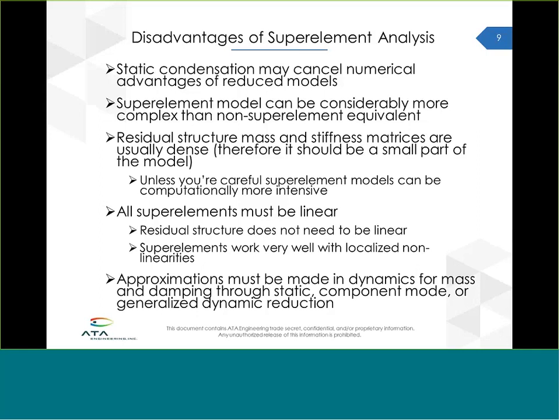Superelements must be linear, so you are reducing a portion of your model once and then combining them together, so the response of that superelement is always linear. The residual does not need to be linear, and I'll get to what the residual is, but that's what's left over after you've done all your reductions and combined them together. So the way that you combine two superelements together, you could have a nonlinear gap in there or nonlinear spring or something, but the contents and the behavior of a superelement is always linear.